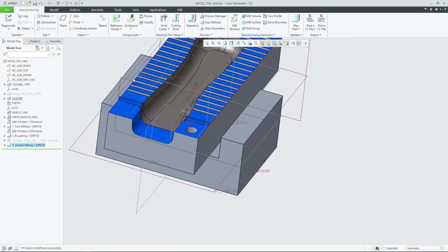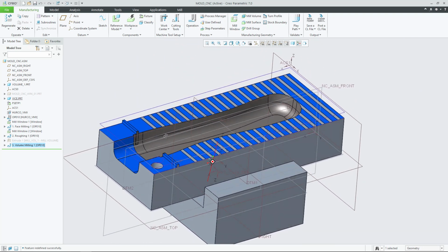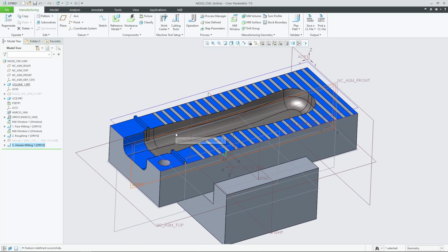So in that way we can create our overall CNC program and the specific sequences themselves with actual real world values, rather than just accepting the default values for speeds and feeds that Creo generates, and rather than making up the tool dimensions that would be our ideal tool for the job. We are actually basing our tool dimensions on real world tools.